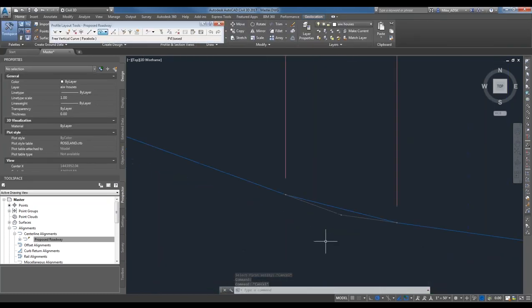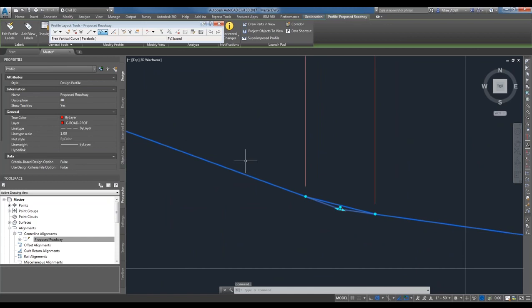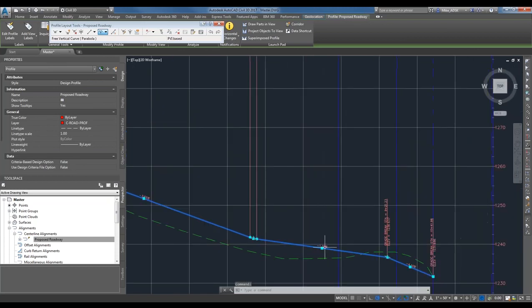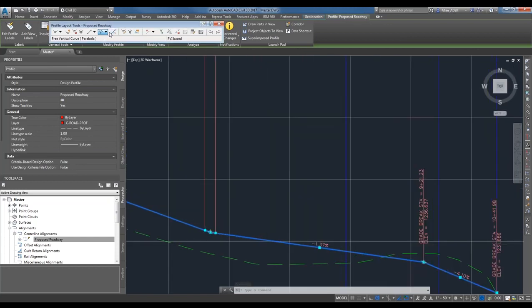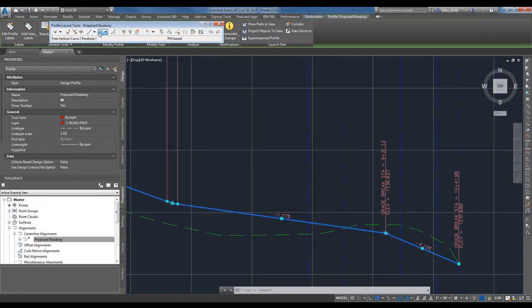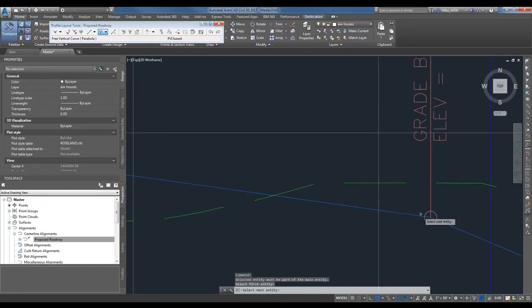You could actually see that now it's not just a bump. You could actually see that it's a nice little radius, nice little curve, so that it's not as hard. You could also continue doing that for the rest. And each time it's going to ask you, do you want to use the same radius? Do you want to change the length? Pass through K. So I'm just going to keep it the same. Use 800.